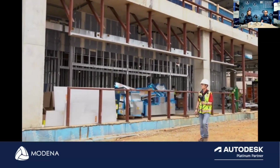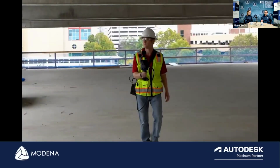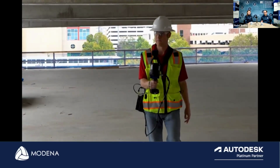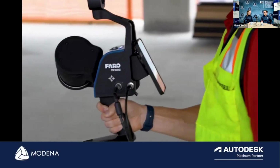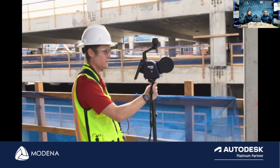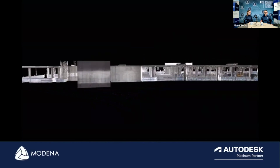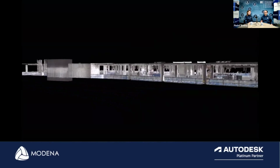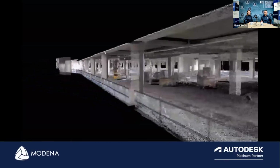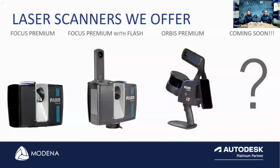What the scanner then does after the laser measurement is it takes photographs up to 266 megapixels with the internal camera of the scanner. With the camera on the Focus, you get a 13 megapixel photograph. And then that photograph basically converts to your point cloud at the end of the day, with the RGB values from every single photo taken placed onto the XYZ values of the laser scan dots to provide you this quality of data that you see on the screen. So the scanners that we have on offer from the Modena side is the Focus Premium.